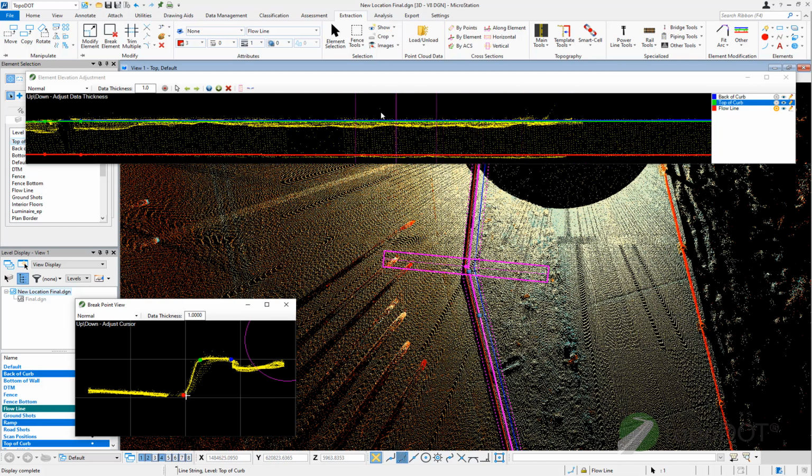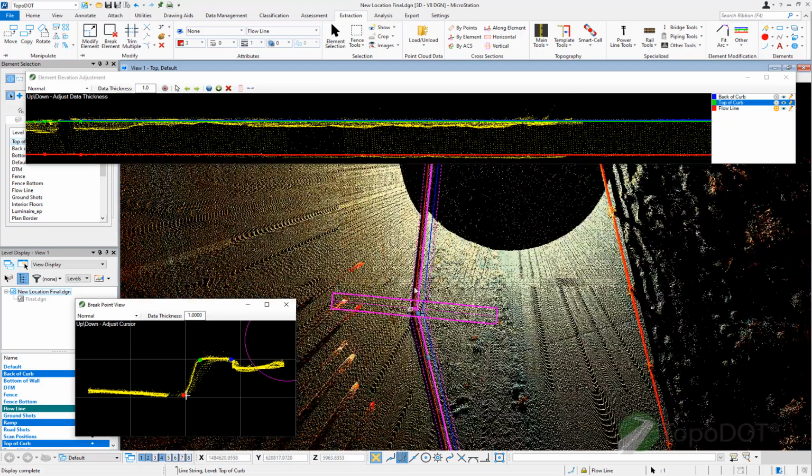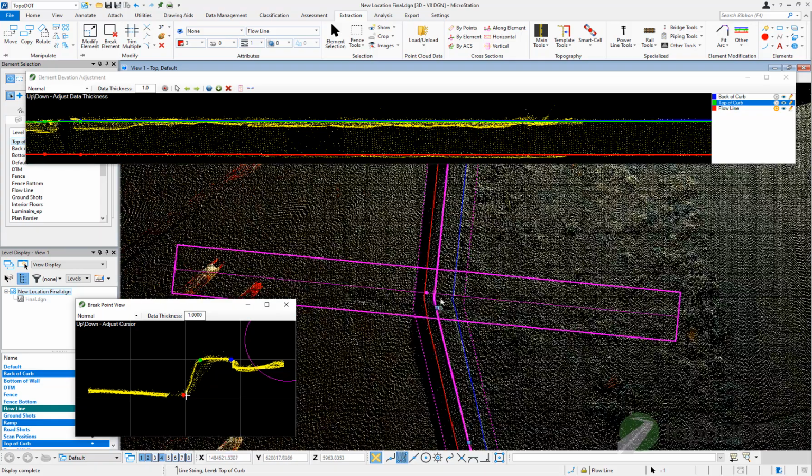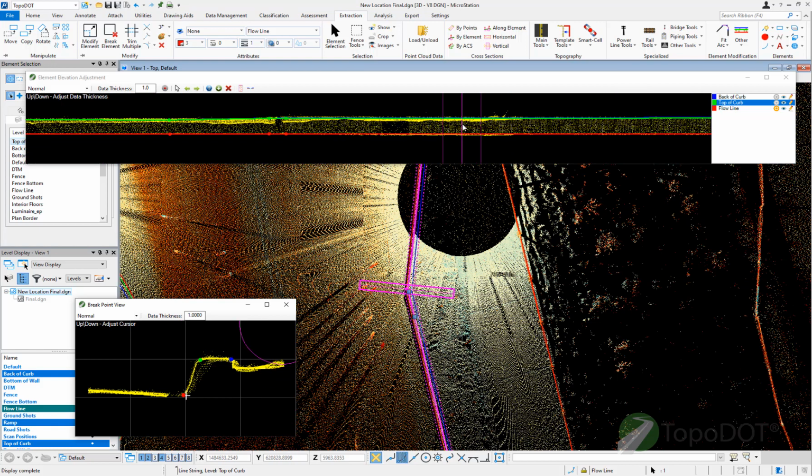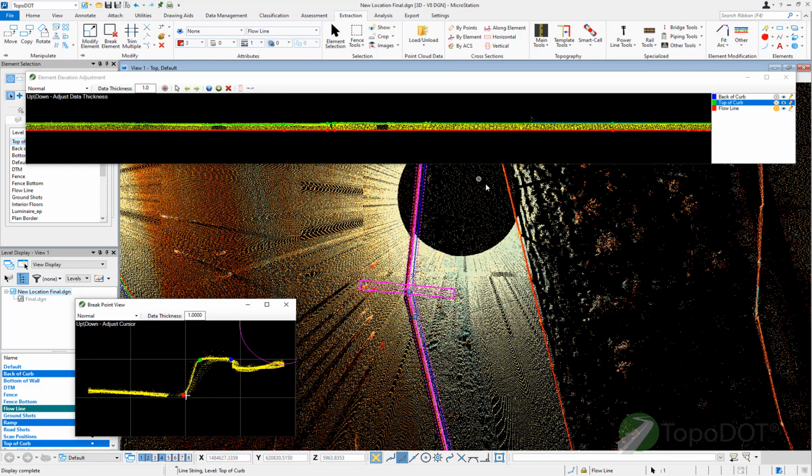Okay, so you can apply all of these changes where they're happening. We can see that this is an especially tricky section because that's where there is a change in direction, and that's why we probably needed a couple more nodes there. Okay, so even though you're seeing 2D views, so cross section, front face, and top view, this is a much more accurate way of interpreting the elevations of your results than trying to see it in 3D.